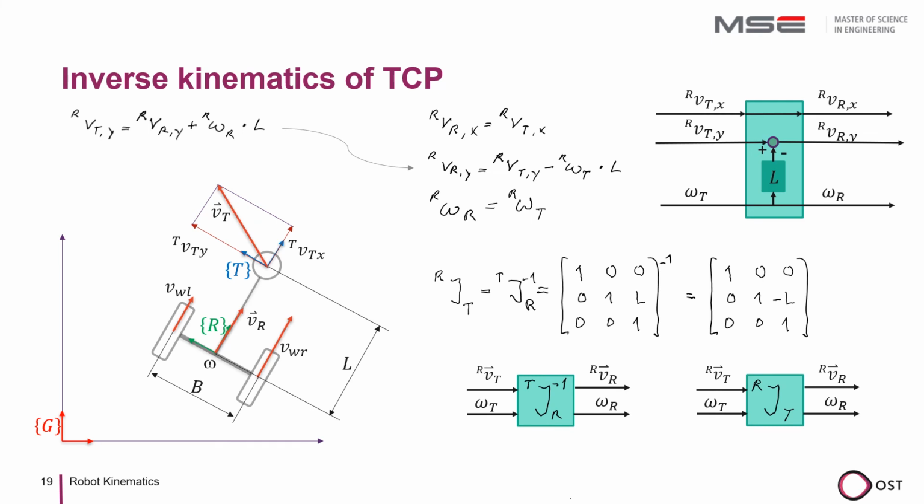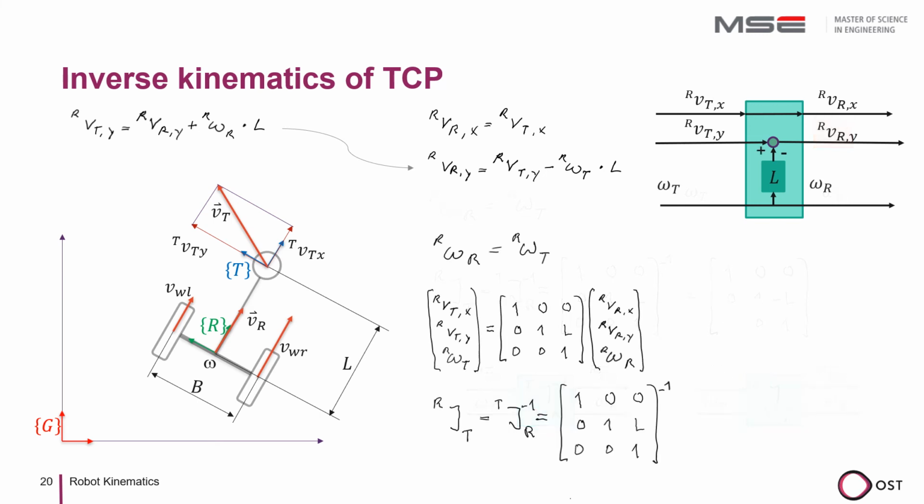However, the solution I found has a velocity orthogonal to the direction of travel of the wheels in the robot coordinate system, which is why it only makes sense if I use an omnidirectional drive. But if I have wheels, VRY must be 0 in the robot coordinate system. From this constraint, I can determine the rotational speed omega, which is now no longer freely selectable.